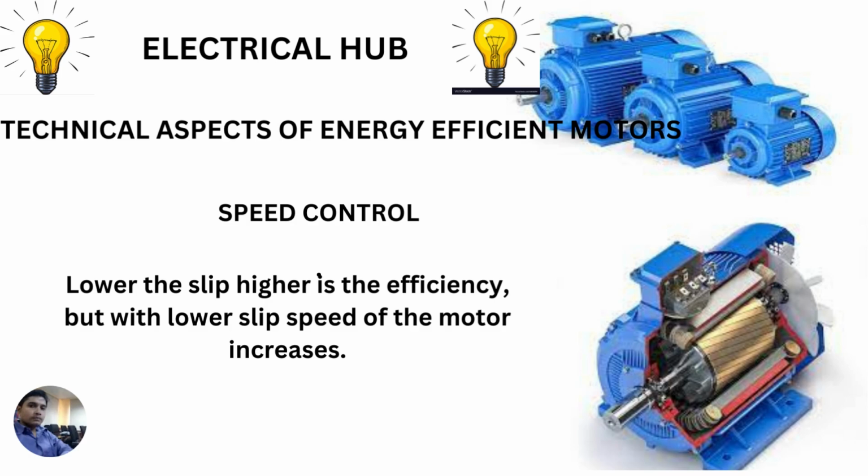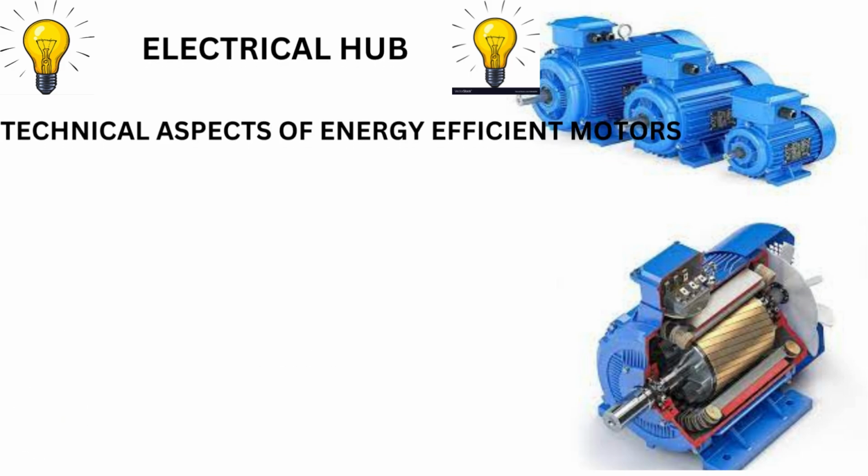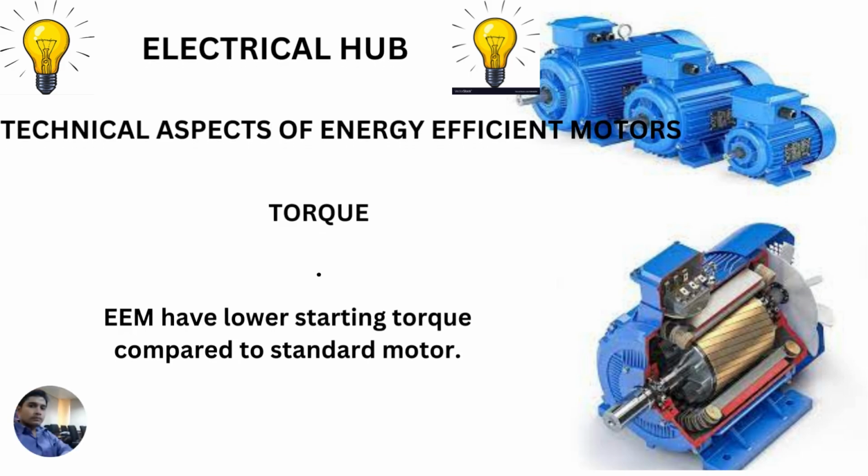So while we are purchasing an energy efficient motor, we should take notice of what the previous speed of the motor was and what the present speed of the motor is, because the variation in the speed may affect the operation of the motor. We should also be aware of the torque. The torque of the energy efficient motor is lower compared to the standard motor.